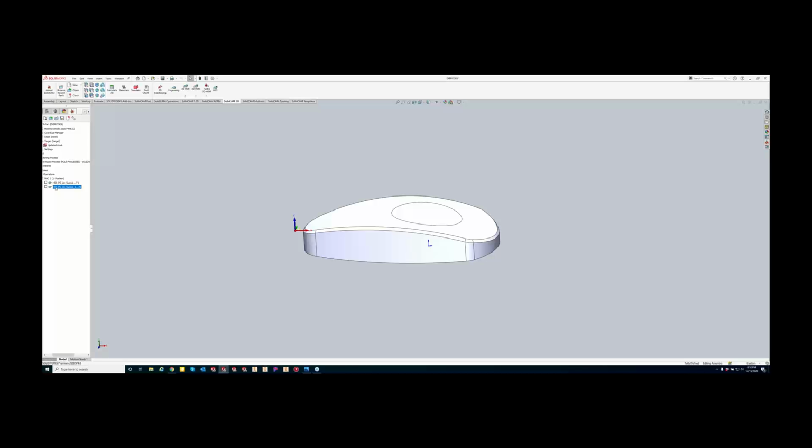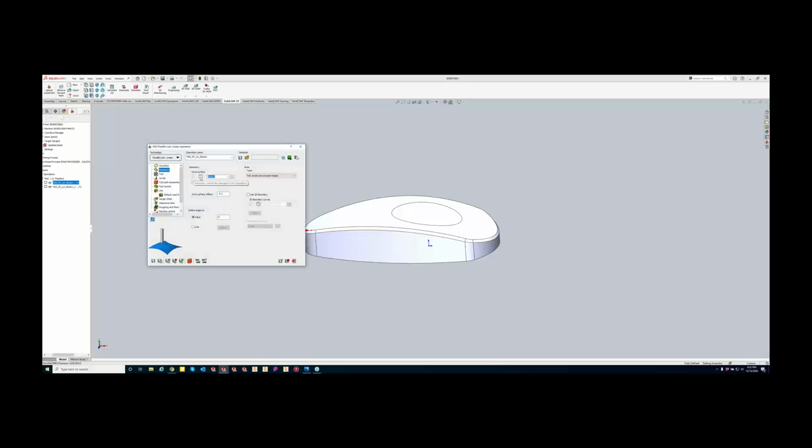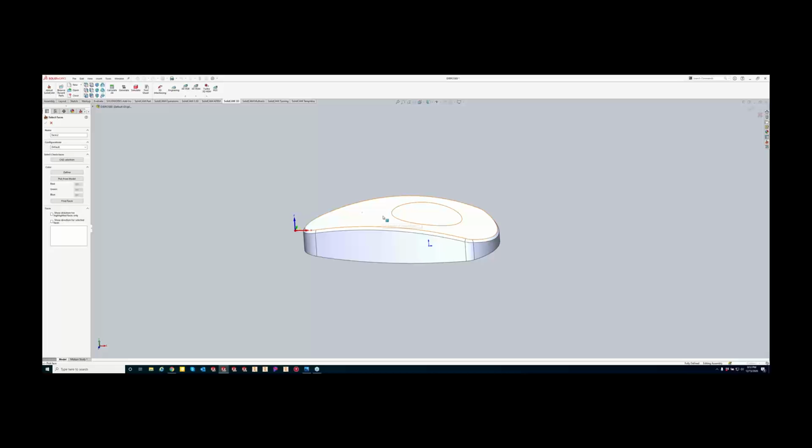do you want me to do that as HSS again? Yeah, HSS again. But I mean, we showed off the ease of use for clearing that gap using the links and having it just follow that surface. But when it follows that surface, it's going to be doing that at the normal cut speed. So depending on what materials you're cutting, how slow that's going, you're going to find yourself with a lot of wasted time going over a large gap like that. So I was wondering if you can show off the feed control zones in the tool settings.